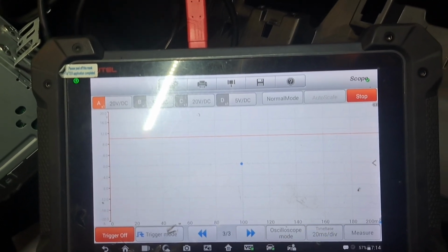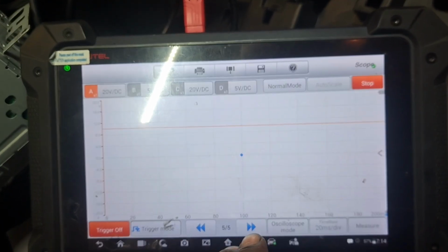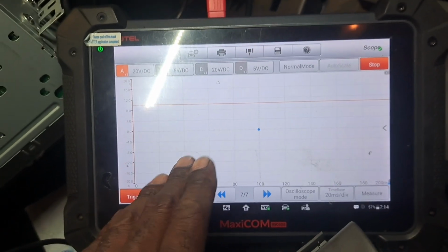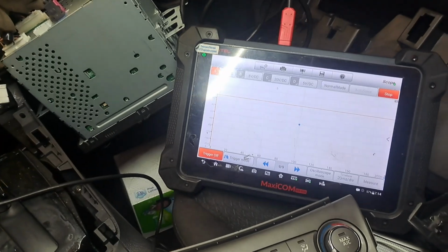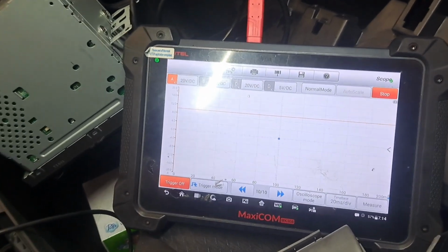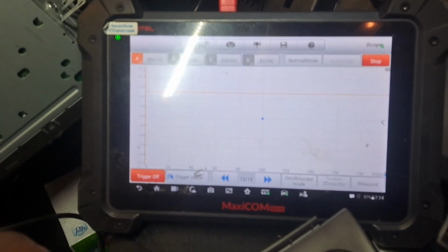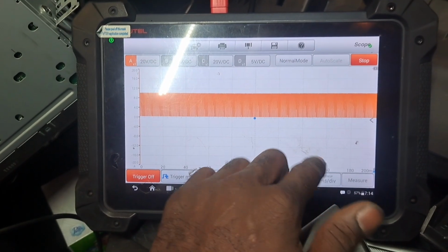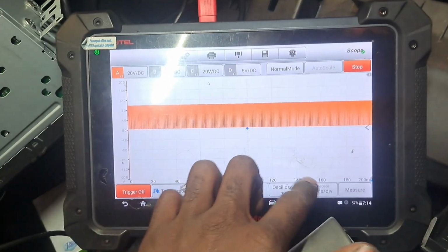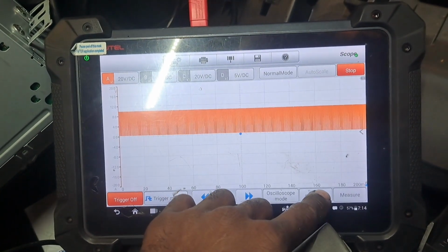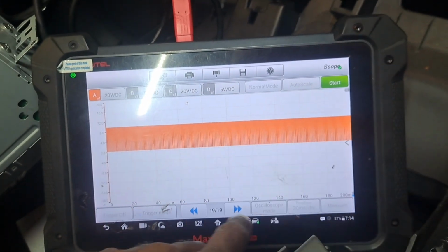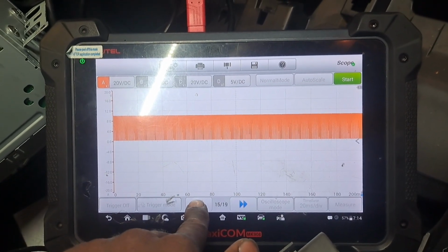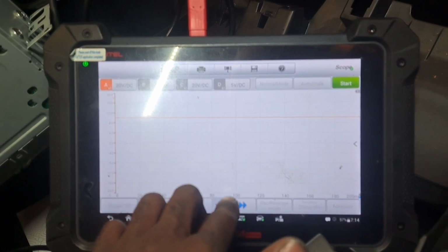The blend door and the mode door are going through a testing phase, it seemed like. There's no PWM coming from the amplifier at the moment. So we're just gonna wait on that. I should have it on. Yep, there it go. There it go. So it just came on. Let me stop this. Go back. It just pops on, just like that.